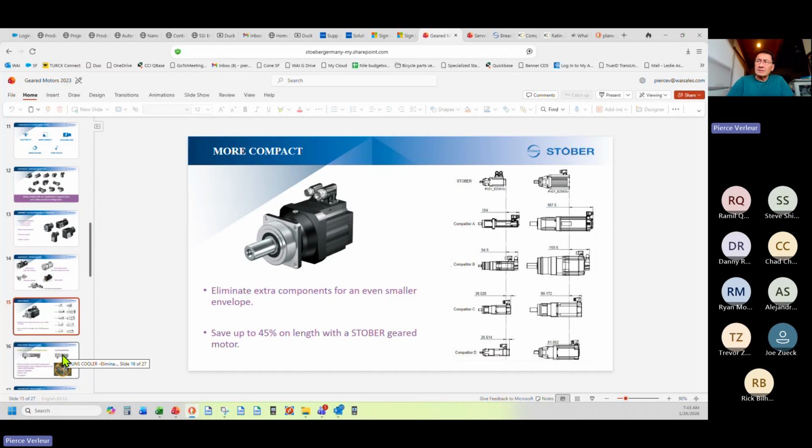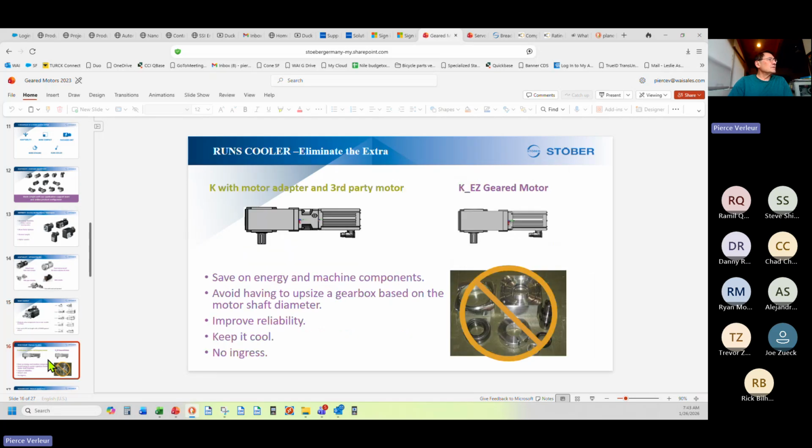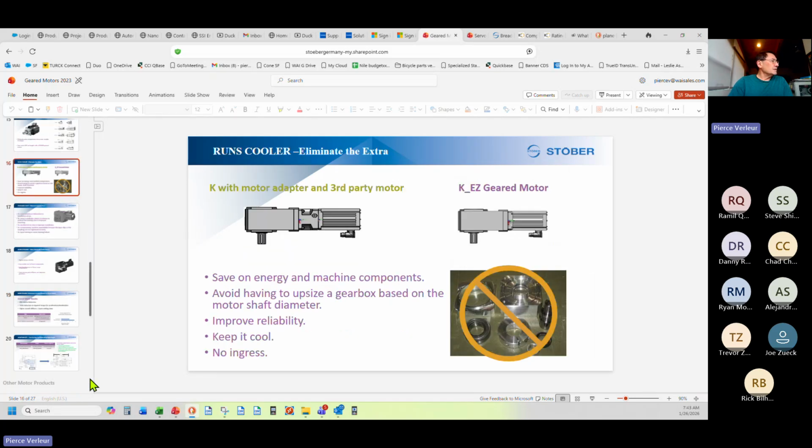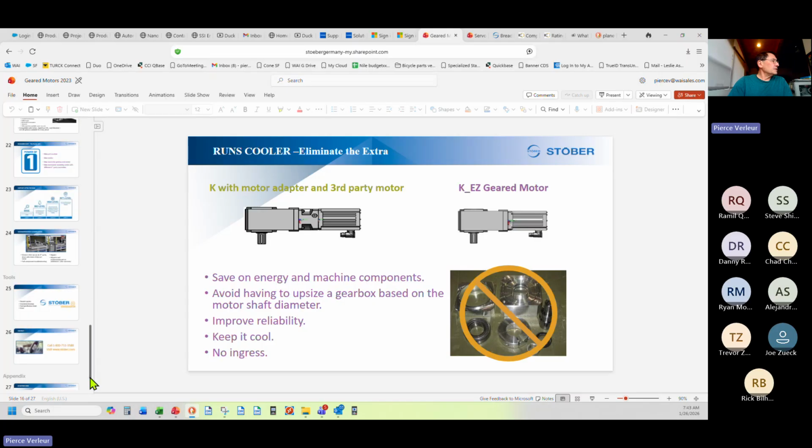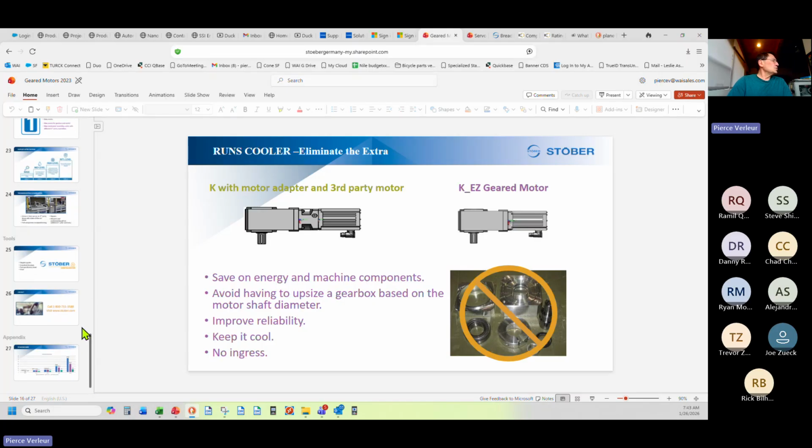Most holding brake based servo gear motors will allow you 1 to 2 e-stops. After that, it's kind of like your bicycle helmet. They tell me if you fall down and crack your bicycle helmet on the ground, you're supposed to replace it. So holding brakes for e-stop, once and done. This company makes a product that I want to point out to you because I'm quite impressed with it. And it's called Sure Stop.